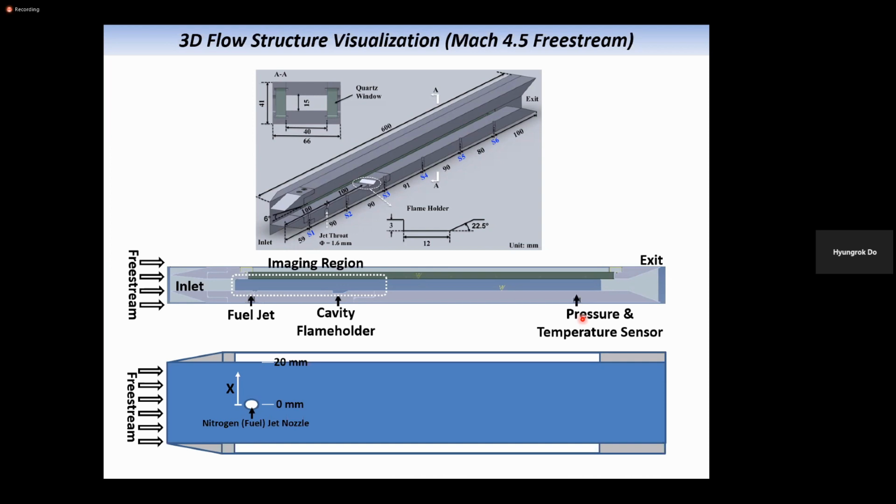In this case, we have used fused silica, which is transparent from UV to the visible range. So if your light source is in the UV to visible range, then you can use fused silica or quartz crystal windows. If you want to execute laser absorption spectroscopy, like for CO2 or H2O, and some CO2 and H2O lines are near the IR region, a fused silica window should be fine.